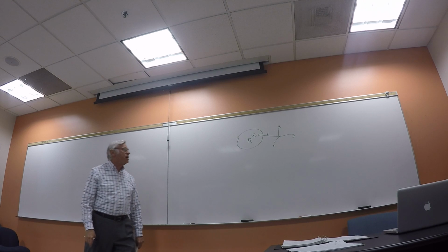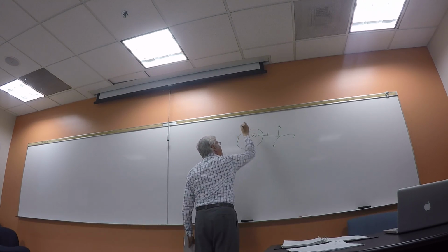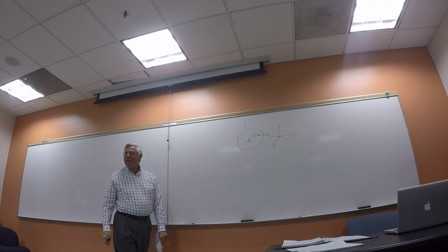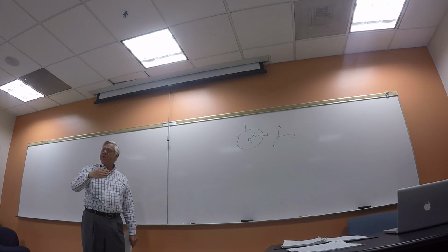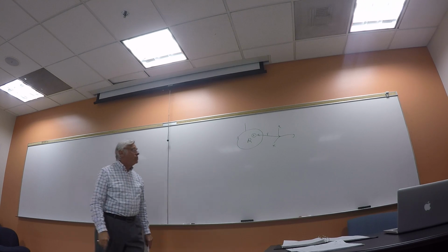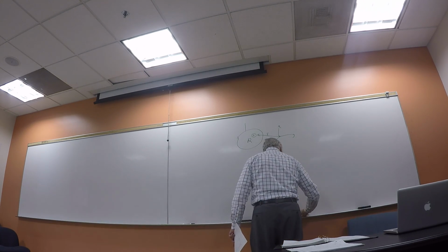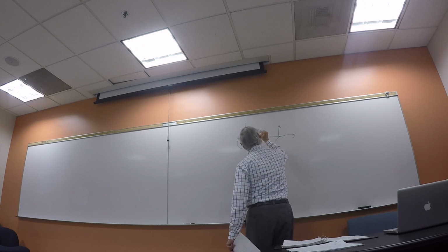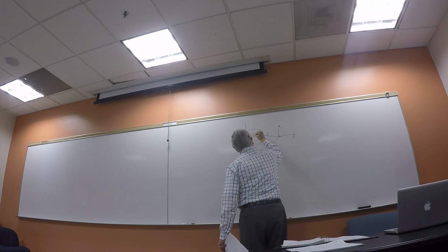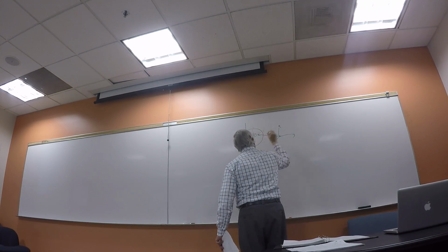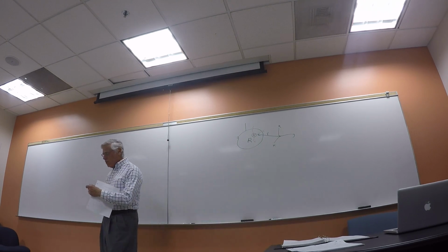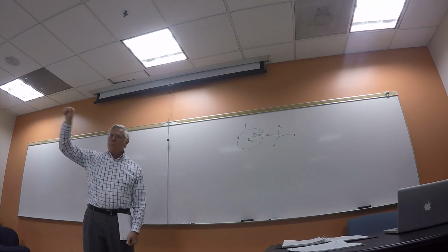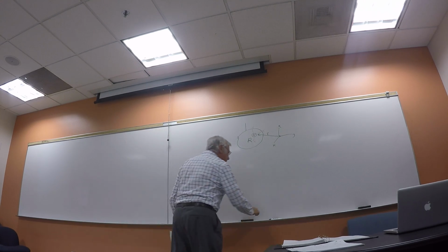There's also rotation. This thing may have antennas on it that have to point to certain points on ground stations, right? So it's not enough just to know where its mass center is, but you also have to know its orientation relative to that frame. So usually what people do is they'll take what's called a body fixed frame over here. I'll call this maybe X prime, Y prime, Z prime, okay? Not to be confused with X, Y, Z. And that's a body fixed frame. So as the body translates and rotates, that frame just follows the body motion, okay?